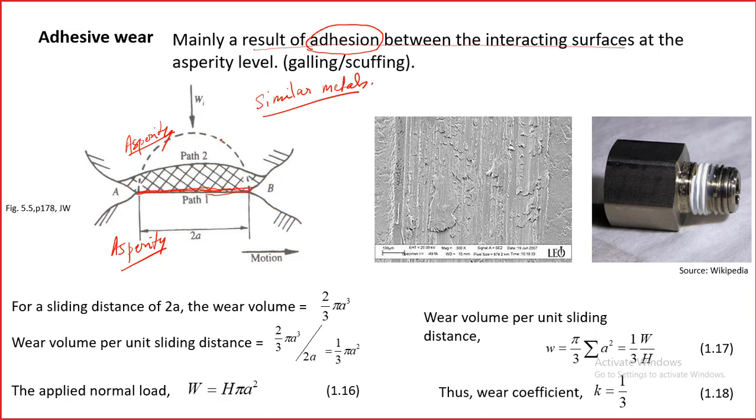Then what will happen is, because we are applying some motion or shear force, the failure, or disconnection, will happen not at this point, but rather at some other points. So path 2 is the shearing path. Although we can think that the shearing should happen here, because first of all the cross-sectional area is small compared to any other point, and another, this interface is full of defects. This is not one single material, there are a lot of defects. So therefore any kind of sliding should happen here, not another place.